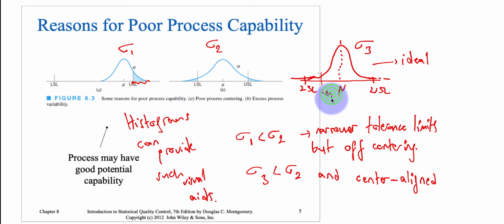And the upper, maybe it is bad writing because I'm using the trackpad, sorry about that. Let's suppose that this is the lower natural tolerance limit, and this is the upper natural tolerance limit. When the process quality is good, the natural tolerance limits will be inside the specification range, like that.